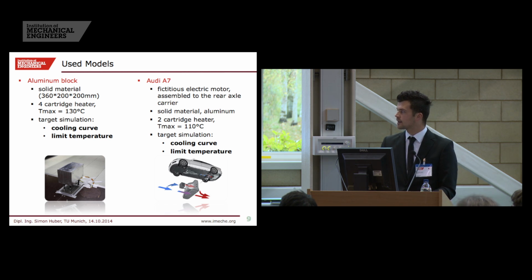Like this I can get a maximum temperature of about 130 degrees, and the simulation target is to simulate the cooling curves. How long does it take if I have the block in the wind tunnel, and I switch off the heating, how long does it take to cool the block down? And of course the limit temperatures, what is the maximum temperature I can get if I have convective cooling.